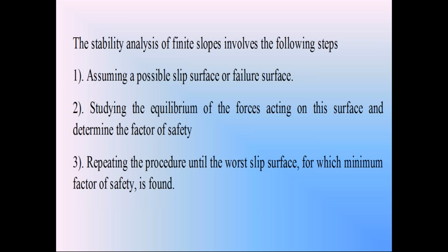So coming to the procedure of stability analysis of finite side slopes, first prepare the plan of the embankment, the earth dam, or the canal slope on the graph sheet. After preparation of that plan, consider an assumed failure surface in that plan.